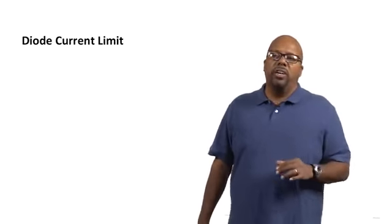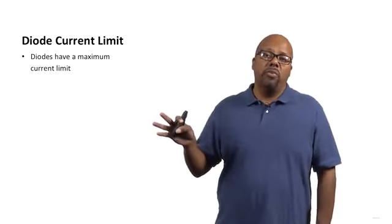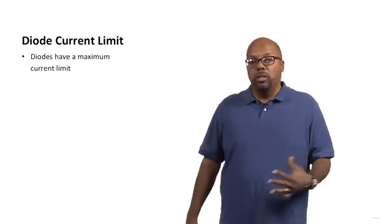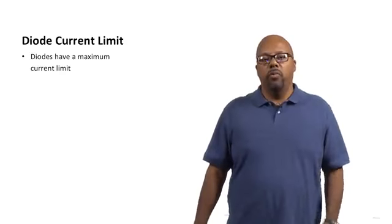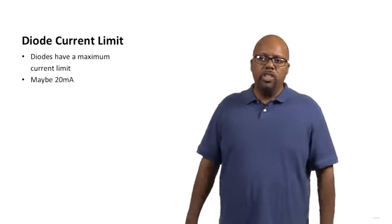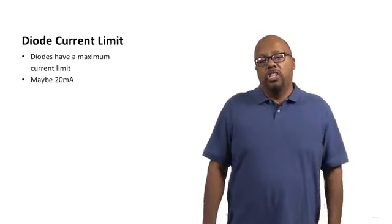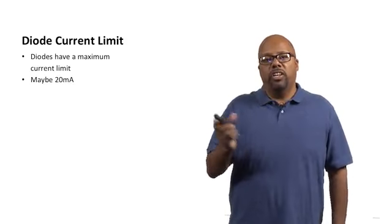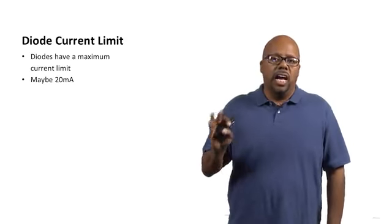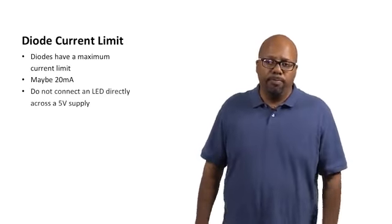Reverse bias is when the anode is negative with respect to the cathode. Another property of diodes is that they have a current limit. They have some maximum current, and you should not drive them with more than that current. You can probably push it a little bit, but it will wear down more quickly. And if you drive too much current, it'll just blow up and it'll never work again. When I say blow up, it might pop, and you just will never see it working again. For typical LEDs that I use, 20 milliamps is the current limit. This is also the limit for the LEDs in your kit, if you got the kit. If you push more than 20 milliamps through it, it will die pretty quickly.